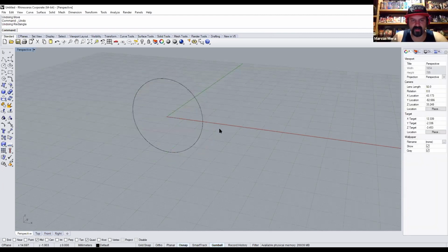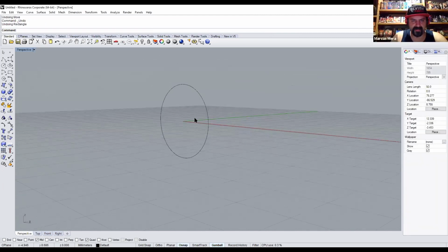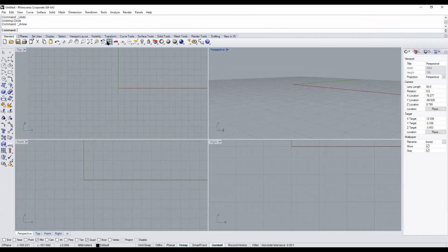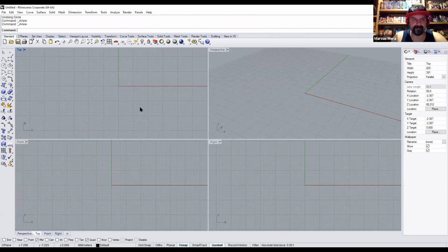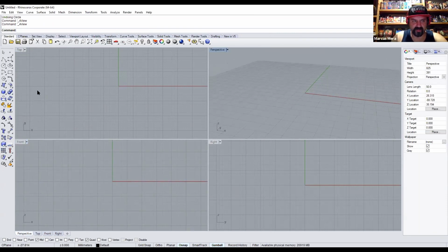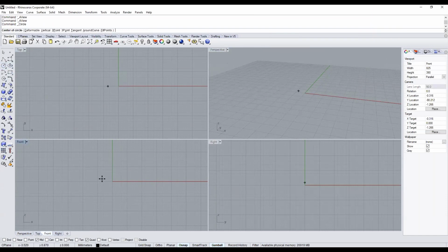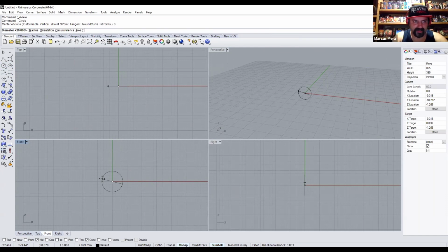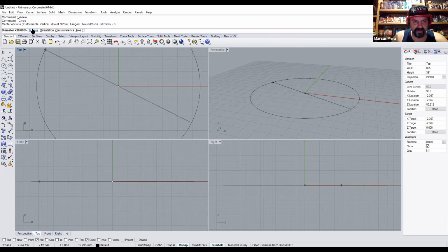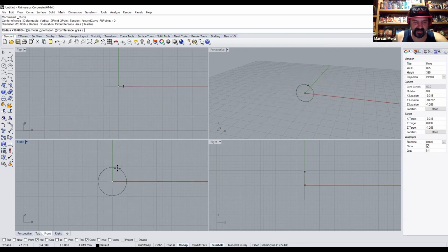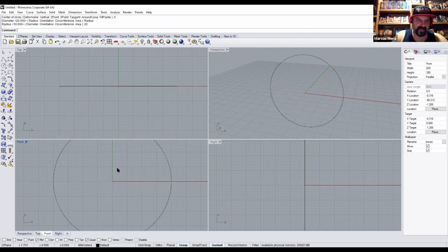All right. So let me just go from the beginning. Okay. So basically, I do the front view because the front view is like your finger going through. So I'll show you what I mean. And I believe 20 millimeters is less than a finger size 6. I forgot exactly. I have to look it up. But just be careful because when I have it set to radius, if I was to switch it to diameter and type in 20, it's going to be like double the size.